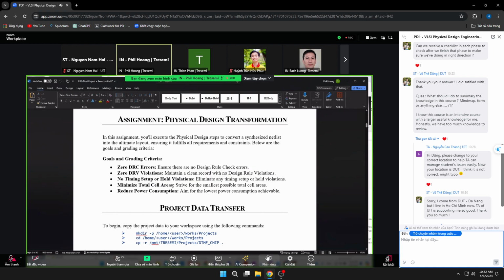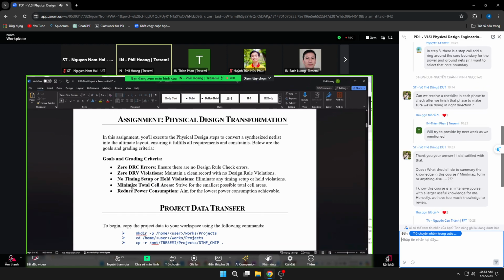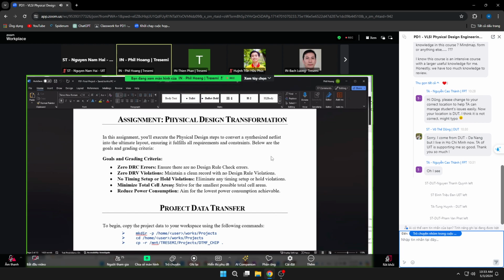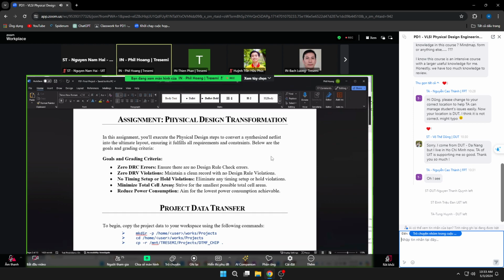And then after everything is done, you pay attention to total cell area. Total cell area means just the standard cell areas, because the macro areas are fixed. So why is this important? If you meet timing and you have everything clean, then the total cell area will tell how efficient your design is. You can meet timing, but if your cell areas are bigger than others, that means you are consuming more power, so you waste more power. Then the other design is better: same speed but less power.